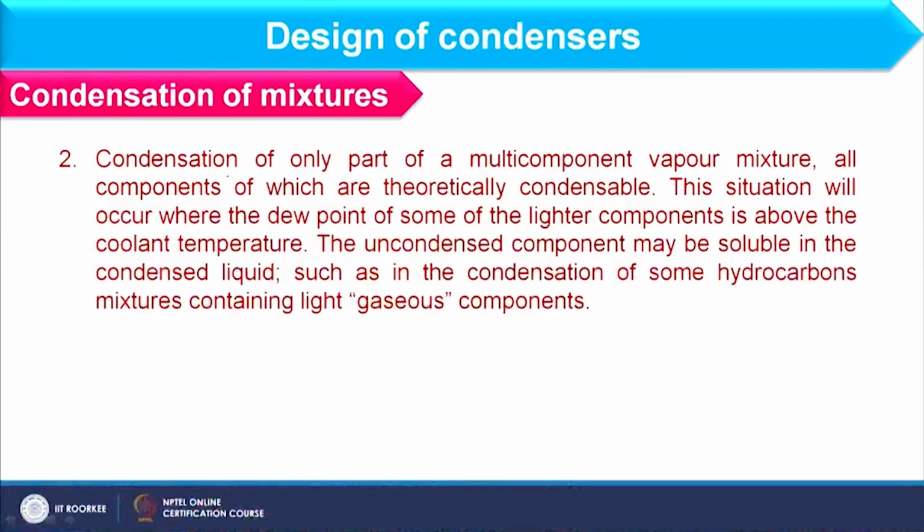Further, condensation of only part of a multi-component vapor mixture, all components of which are theoretically condensable. This situation will occur where the dew point of some of the lighter component is above the coolant temperature.